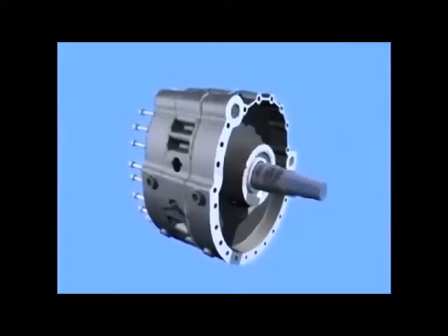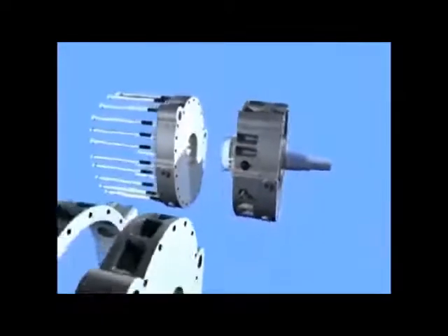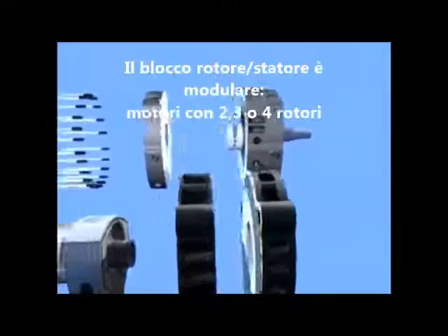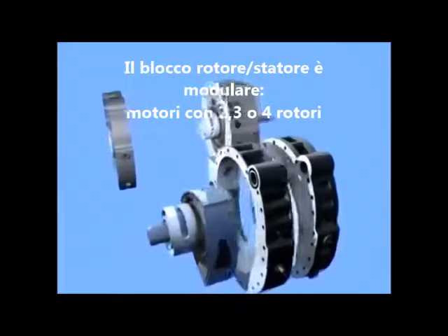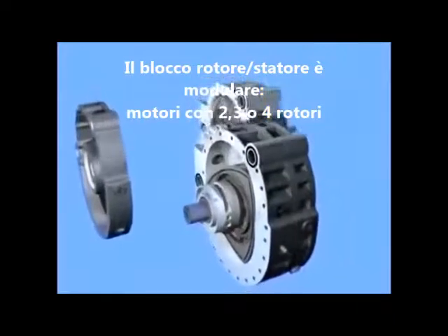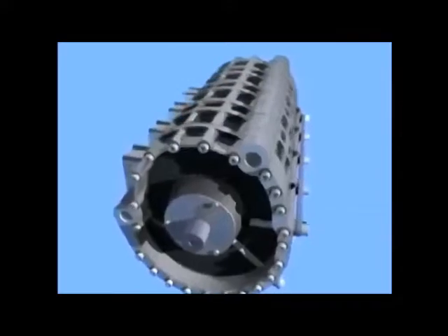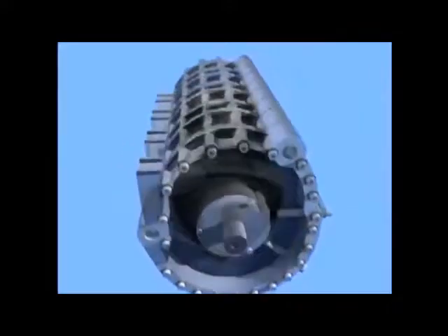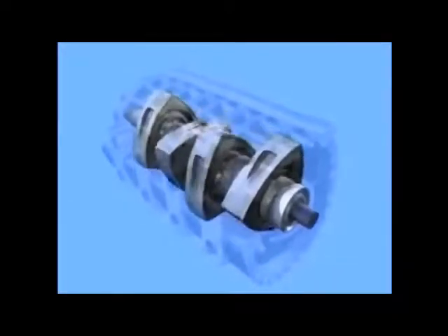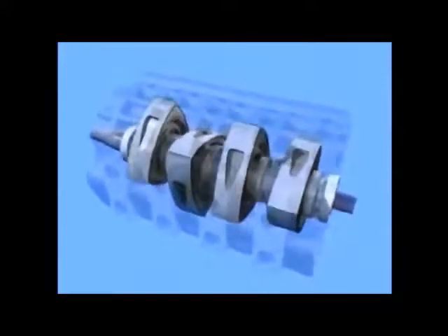The modular design of the COFA multi-fuel Wankel motor allows the simple extension of the motor to create a 2-rotor motor, using exactly the same end housing together with an identical combustion chamber housing and a connecting housing. Here we have quite simply created a 4-rotor engine. With 3 combustion chambers per rotor, this is equivalent to a 12-cylinder piston engine.